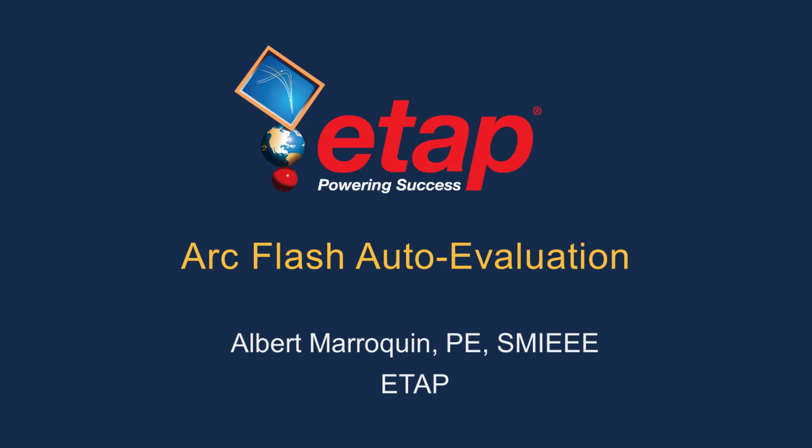The concept that we're going to talk about today is called arc flash incident energy evaluation, or arc flash auto evaluation. This concept was born a couple of years ago from an idea that I had while thinking about how to improve the methods that we had available to evaluate the incident energy. Well, this method or concept relies on evaluating the incident energy using time current characteristic curves.